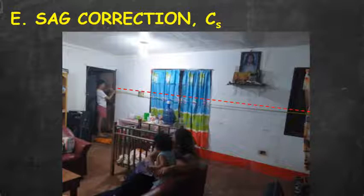So, sag shortens the horizontal distances. Diba? Nasa-shorten niya yung ating horizontal distances between the graduations. So, it's always a negative value. So, your sag is always a negative values. It can be diminished by a greater tension. Pwede mawala yung sag pag stretch natin siya masyado, yung ating tape, nawawala yung ating sag. So, but not eliminated. Pero kung grabe yung ating tension na i-apply, so, hindi siya na-eliminate unless the tape is supported throughout its length. So, dapat support natin siya sa gitna para hindi siya magsasag.